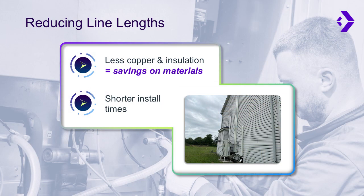And last, another great way to save costs when installing heat pumps is by being mindful of the refrigerant line lengths. This involves carefully planning where to run the lines and strategically placing the outdoor units. The goal is to find the best possible location for the outdoor units, somewhere that meets the manufacturer's clearance requirements, while also keeping the line lengths at a reasonable length. Something to keep in mind is, like the manufacturer's clearance requirements, some manufacturers also have minimum line length requirements, so it's important to consult the manufacturer's guidance when installing line sets and applying this cost-saving measure.